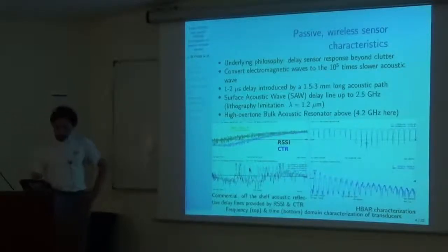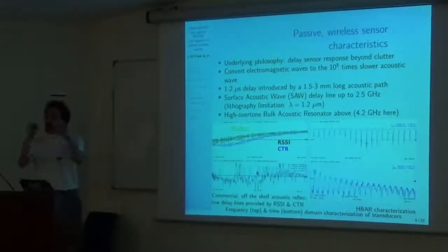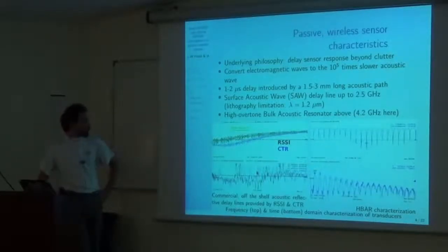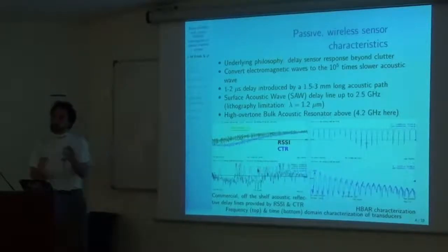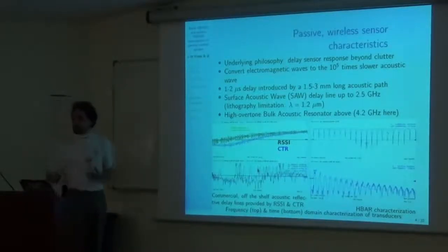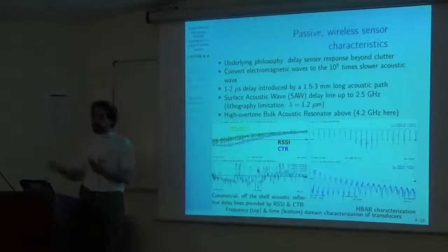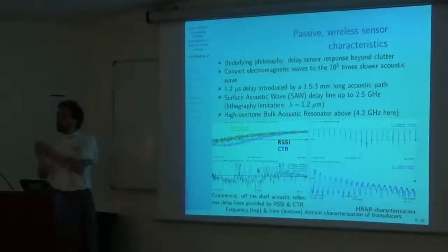If you just want to imagine, the time delay between these echoes is dependent on temperature, because temperature will shrink or extend my mechanical piezoelectric substrate. So if I heat up or if I cool down my sensor, my substrate, I will change the time delay between my echoes.